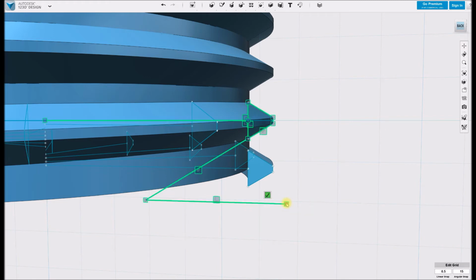It's not going to hit anything else, so just do 90 and then there. The main thing is that you have that 60 degrees, so you maintain that angle following that thread all the way down. It gives it a nice smooth lead in.